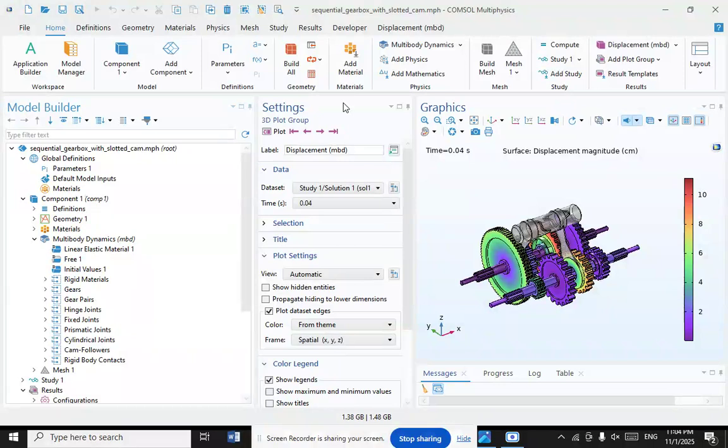These gears are usually spur gears with straight cut teeth, which, unlike the helical teeth used for forward gears, results in a whining sound as the vehicle moves in reverse. When reverse gear is selected, the idler gear is physically moved to mesh with the corresponding gears on the input and output shafts. To avoid grinding as the gears begin to mesh, they need to be stationary, since the input shaft is often still spinning due to momentum.